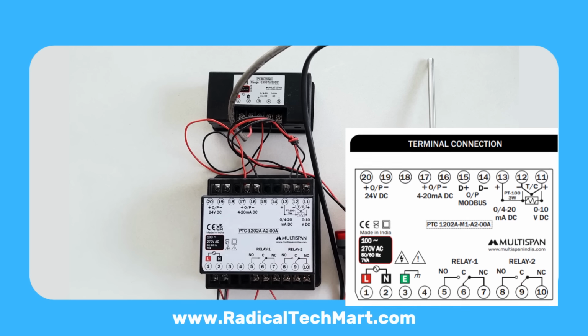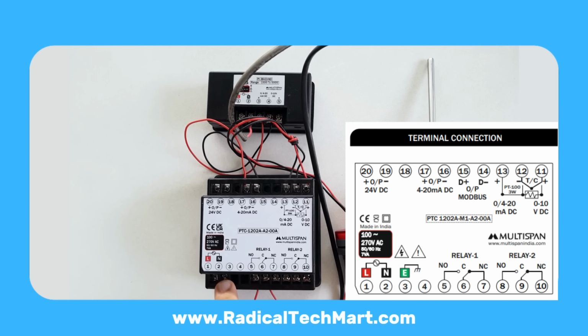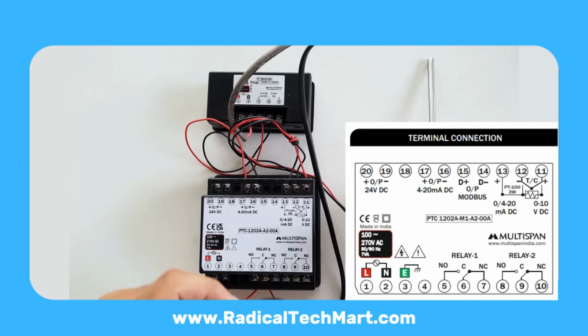Power: give 230 volts AC to L and N. From L, loop a short link to the common COM of relay 1 and relay 2 if needed. From each NO terminal, take an output to your load or to a demo LED. LED neutrals go straight to N. Use cases: R1 can drive a heater, cooler, or on-off control. R2 can drive a hooter, buzzer, valve, contactor, or remain spare.